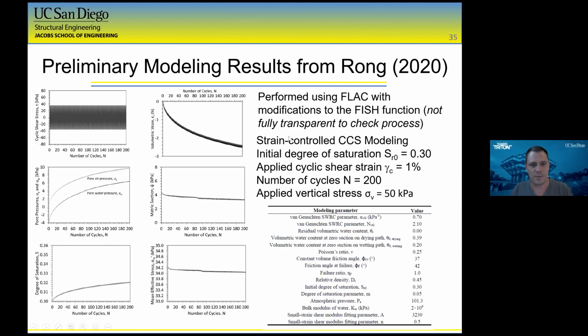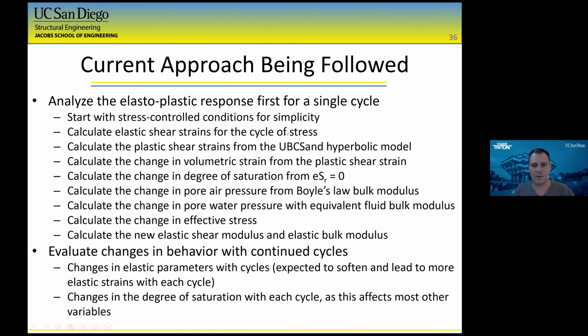So the approach we're using now is to look at cycle by cycle analysis. So we're trying to go through this flow chart to really explain how everything is happening, and then we can use our observations there to refine the pore mechanics that we're using to predict our pore air and water pressures during each cycle.